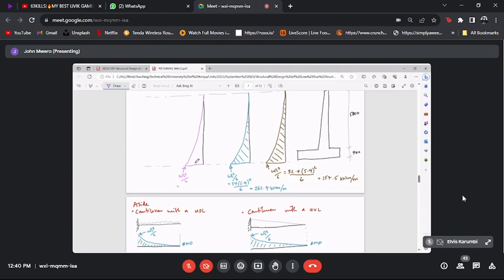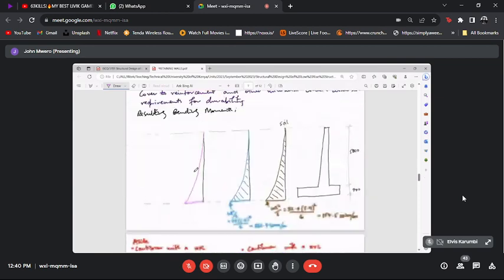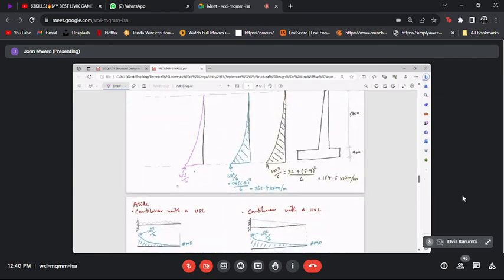So what is W? We come back here and pick value of W is 7. So pick 7. L squared, so 5.4 squared over 2. So say 5.4 by 5.4 by 7 by 2, 102.1, 102.1 kilonewton meters per meter.